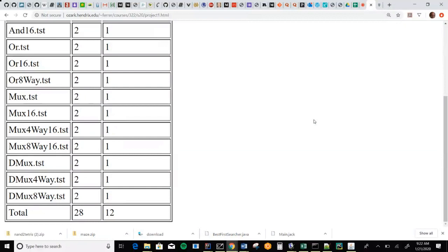Can it work in principle? Well, yes, for reasons we've gone over. Anything with a truth table, you can just build it out, right? But let me give you a little hint. A 4-way MUX just might have some other multiplexers in it as subcomponents. Those just might be useful.